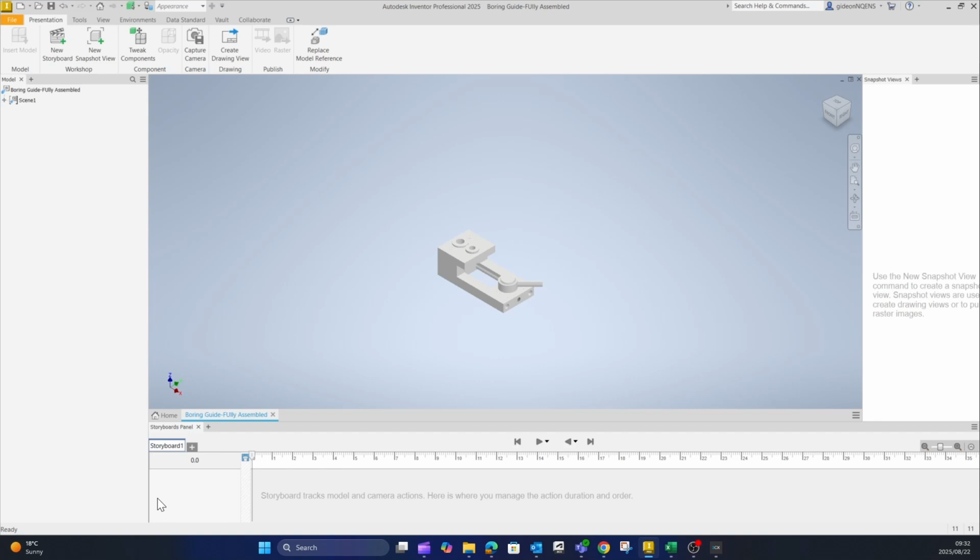And mainly you'll create your assembly and then go into the presentation file and tweak the components to create trails that you will utilize for snapshots to create a nice GA drawing with your parts list and your balloons to see how everything can fit together. Now in this environment I've got Inventor open. I brought in a very small assembly.